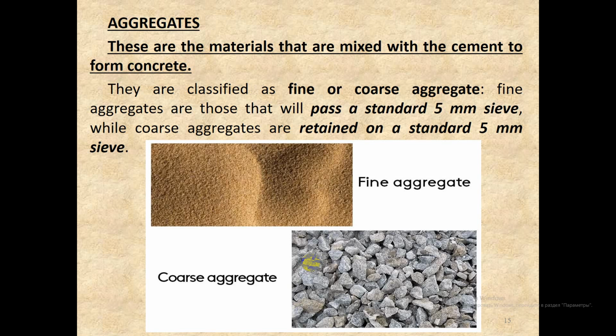It's possible to obtain recycled aggregates and recycled concrete aggregates for use in concrete, which should conform to BS 8500-2, and further, lightweight aggregate is sometimes required and may be natural, but sometimes it's man-made.